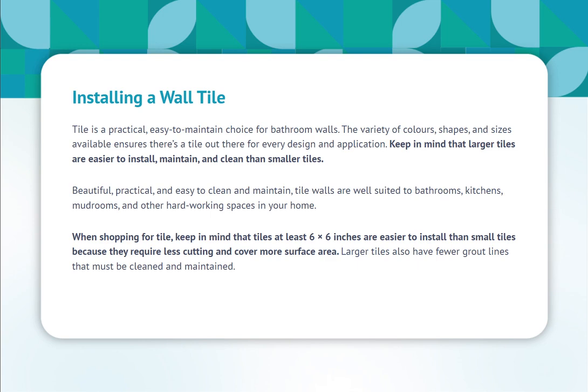Beautiful, practical, and easy to clean and maintain, tile walls are well suited to bathrooms, kitchens, mudrooms, and other hard-working spaces in your home. When shopping for tile, keep in mind that tiles at least 6 times 6 inches are easier to install than small tiles because they require less cutting and cover more surface area. Larger tiles also have fewer grout lines that must be cleaned and maintained.